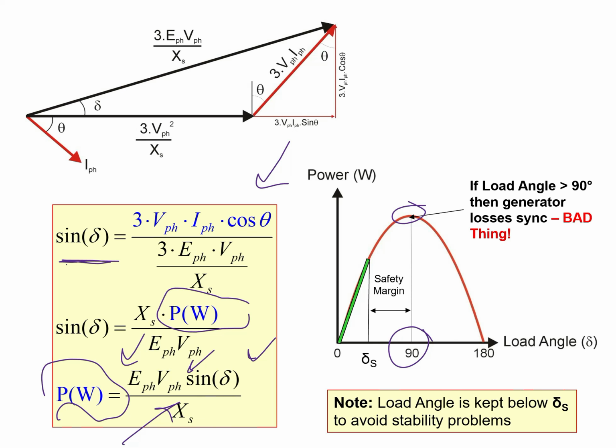So basically what would happen is, as the load angle reaches up to 90 degrees, half a pole of the magnetic poles pitch, the stretched flux lines get broken, and hence the magnetic locking between the stator and the rotor no longer exists, so the motor comes out of synchronism. So that's why we keep a safety margin, and the load angle is chosen to be somewhere in this region.